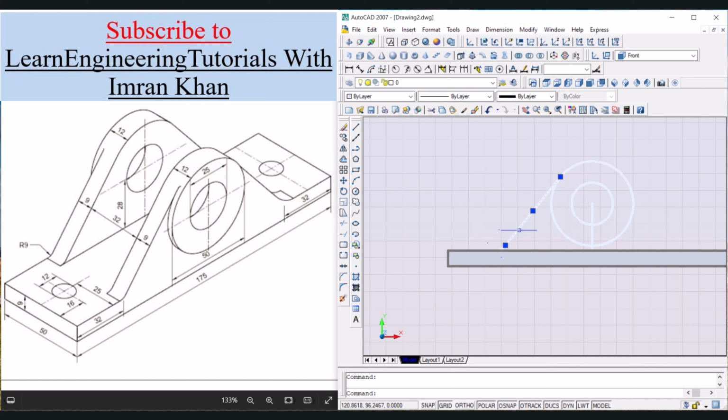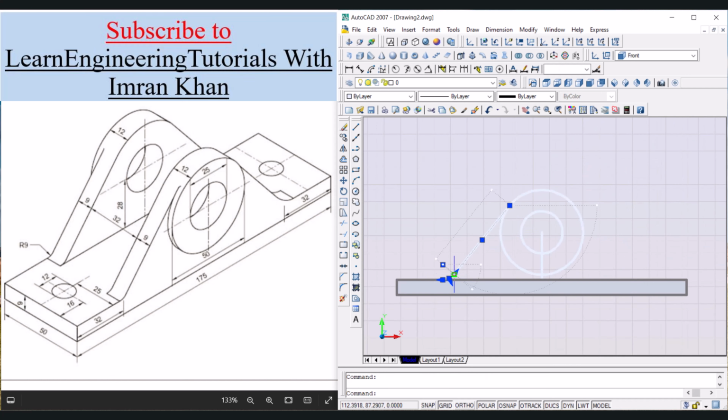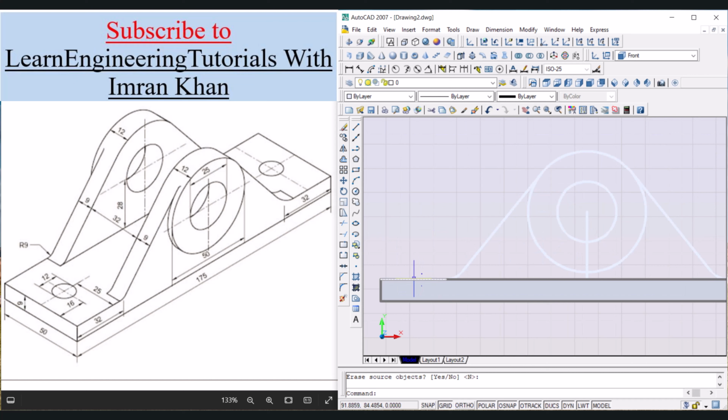Again click on these two objects and mirror them. So click on mirror, click on this point and this point, erase source object, no, enter. Delete this line, this initial line actually, press delete. Now we have to remove this line.